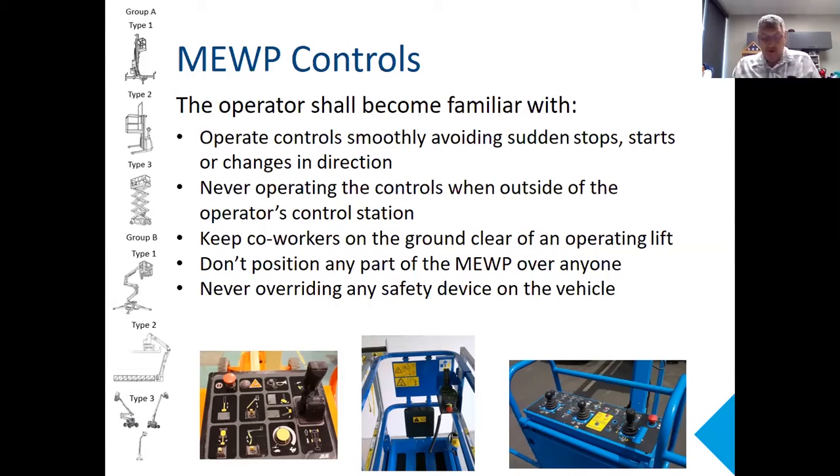Example is if you're using an MEWP and you're renting it, it shows up at 6 o'clock. The operator is unfamiliar with it. You would not expect the operator to be on that lift at 6:10, knowing that he's doing an effective job and in a safe way. Learning as you go is not always the best form of training here. Take your time, it'll pay off. So maybe the day before, get that MEWP and run everybody through it.